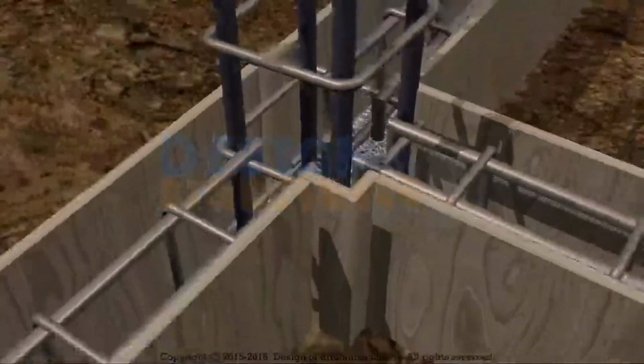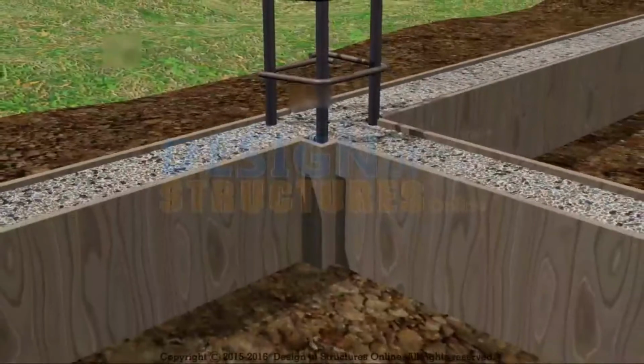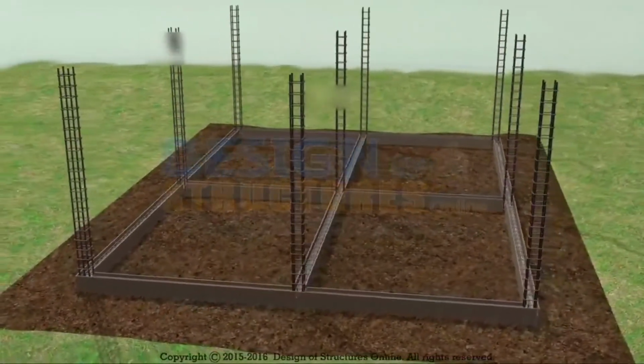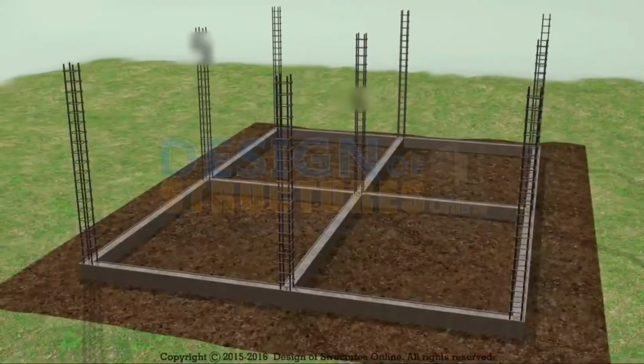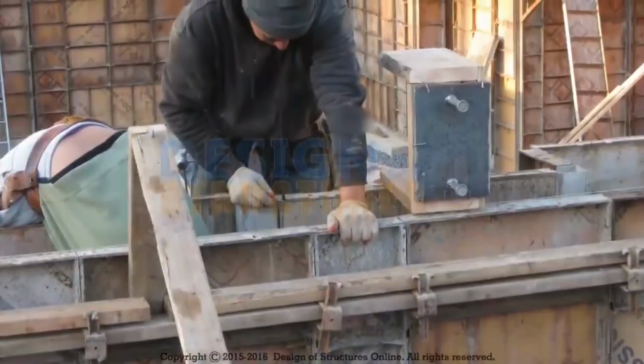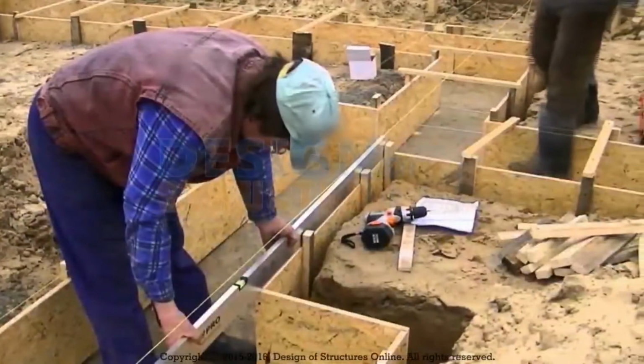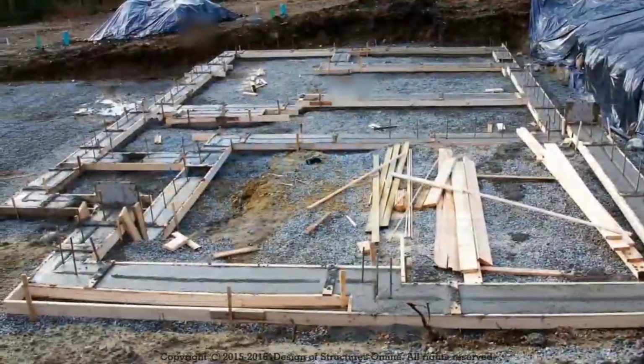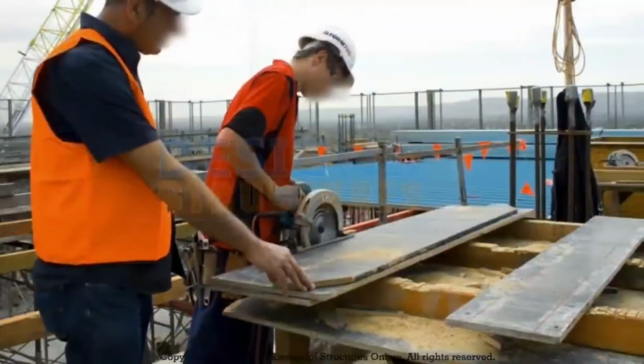Beam concreting. Beam is poured with concrete of the grade mentioned in the drawings. The positioning of reinforcement should be properly aligned. Shuttering parts and connections should be arranged in a way that makes formwork removal easy and simple, and prevents damage to concrete and formwork panels so that they can be reused without extensive repair.